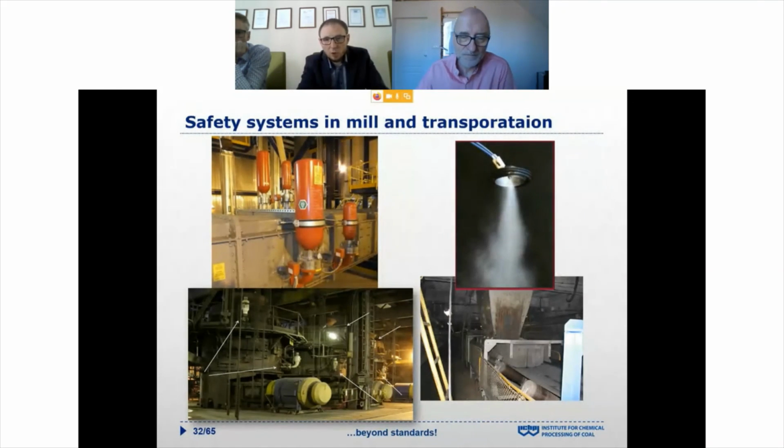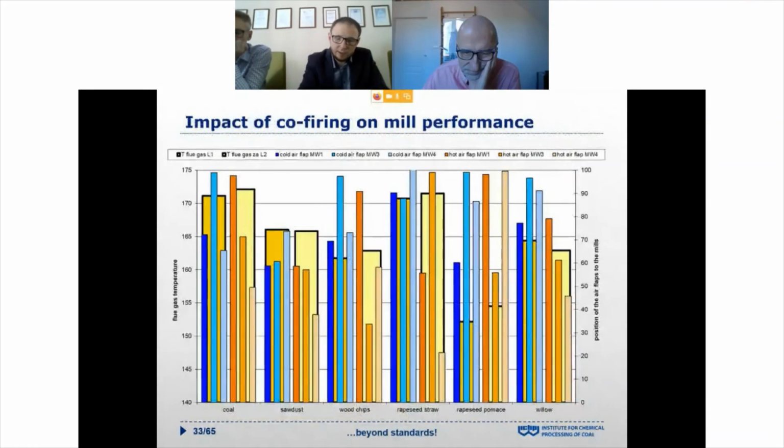Also, another very common solution is to apply fogging, using very specific water nozzles. They create fog-like water and create a safety barrier to avoid explosions.